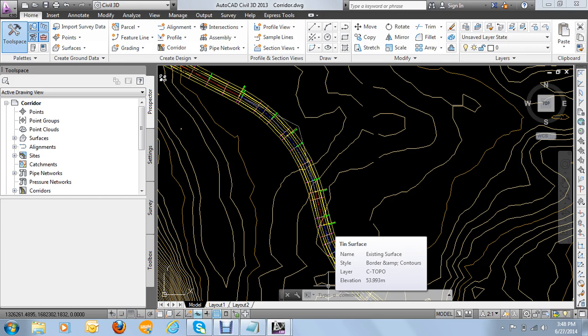Yeah, I know. Another one is, for the design profile, after doing the profile, now you create the design profile. Where is that design profile going to work? Because when you are going to create a corridor, the profile that you are going to select is the design profile.